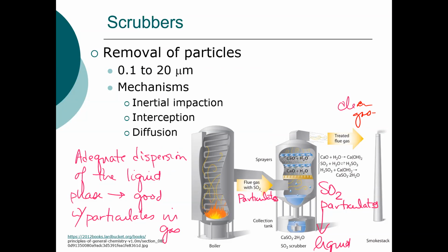We've talked about, with filtration, inertial impaction, interception, and diffusion. Diffusion being for those very small particles, interception and impaction for the larger particles. Here it's not a fiber that you're trying to impact or contact the particle, but it's the droplet. So you can envision the same sort of video, except instead of a fabric, the gas is moving through this kind of maze of liquid droplets.